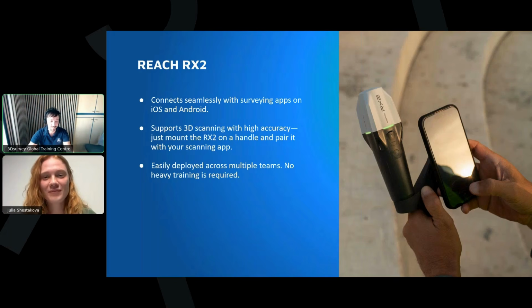I can just confirm everything that you explained already. One more beneficial thing which we figured out when we compared it with all other devices: with the Emlid device, we can get, I believe, 5 positions per second out from the location. And this is super good for our videogrammetry algorithm, because with most other devices we were able to get 1 or 2 per second. So this just gives you a higher accuracy even if you are moving faster during the recording of the video, and it's super important.